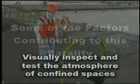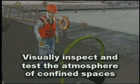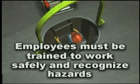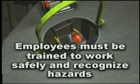Let's look at some of the contributing factors that led to this fatality. Confined spaces must be visually inspected and tested by a competent person to determine the atmosphere's oxygen content prior to an employee's entry. Employees entering confined or enclosed spaces must be trained to perform their work safely and to recognize hazards.